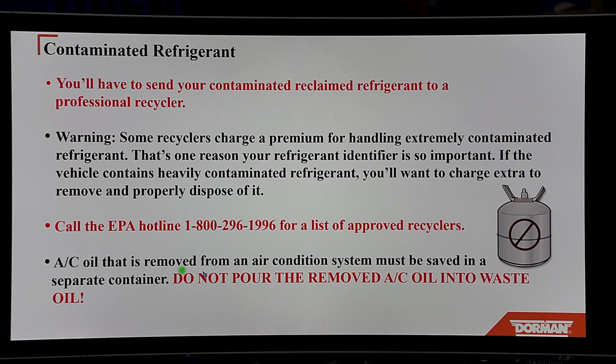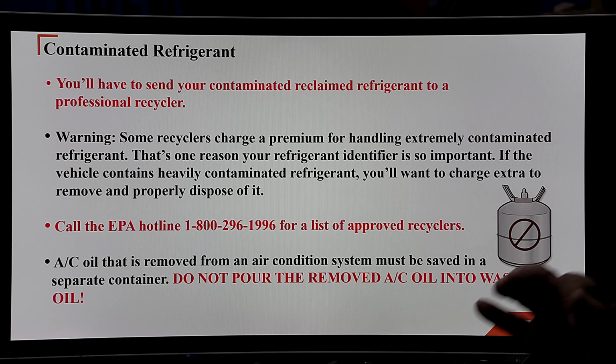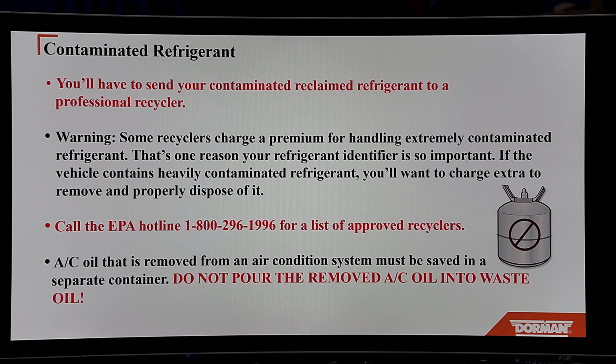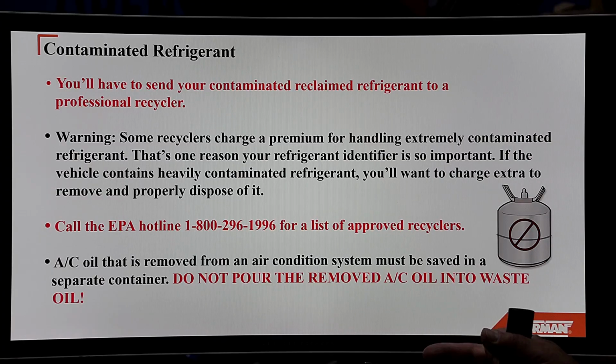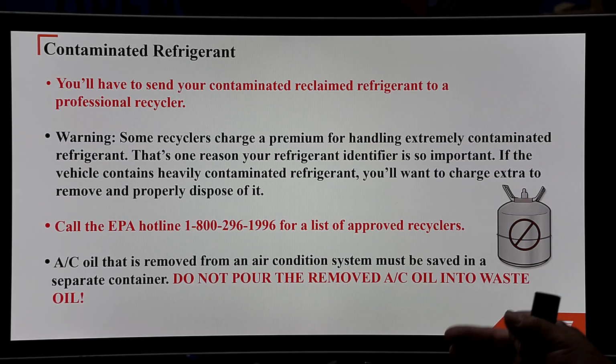AC oil removed from the air conditioning system must be saved in a separate container. Very important. Now, if you burn oil, I'm not the government. I'm just telling you what you have to do. We use Safety Clean to pick up our waste oil, but we give them the oil from the AC system separately and get a separate manifest.